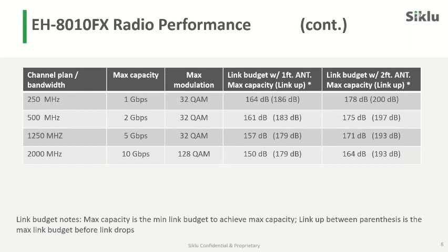The dual transmit power control feature is used when the link is very short, and in that case there is a chance of overload of the far end. So the user would reduce the transmit power to avoid overload in the normal operation of the link. However, reducing the transmit power during normal operation also means that there is reduced dynamic range during a rain event.